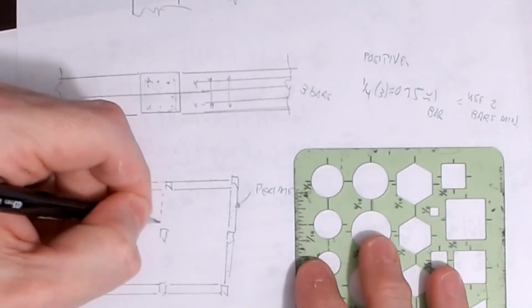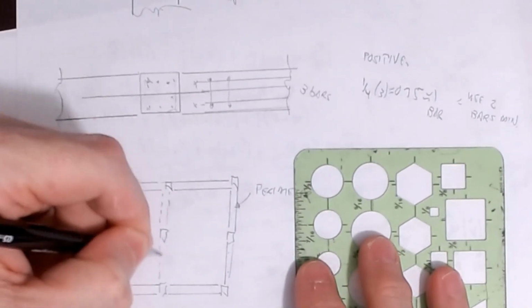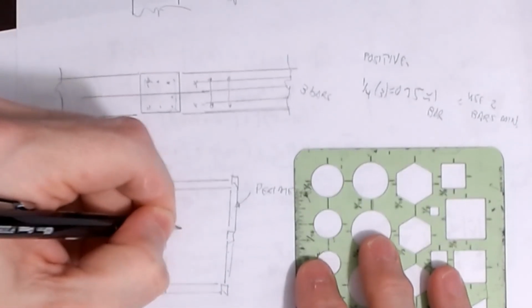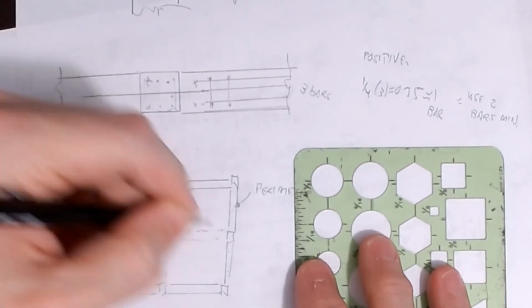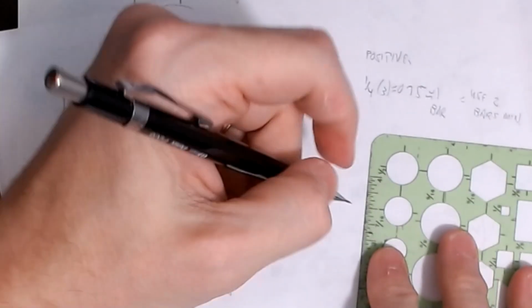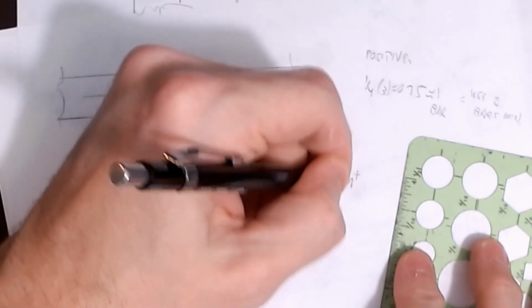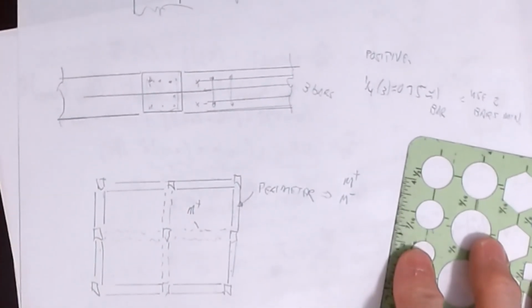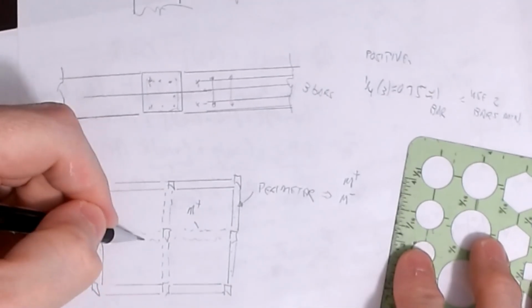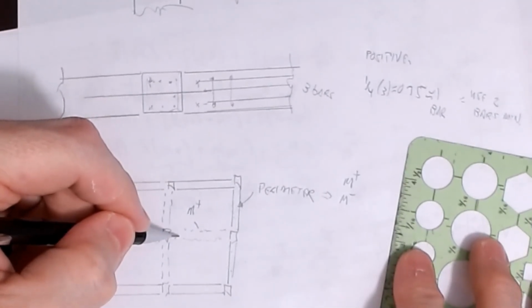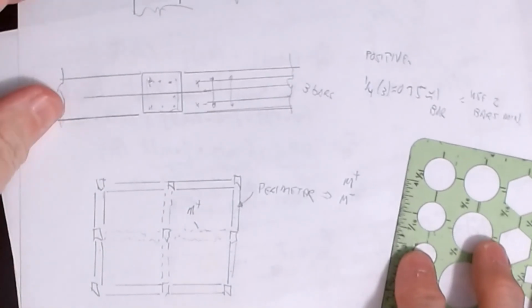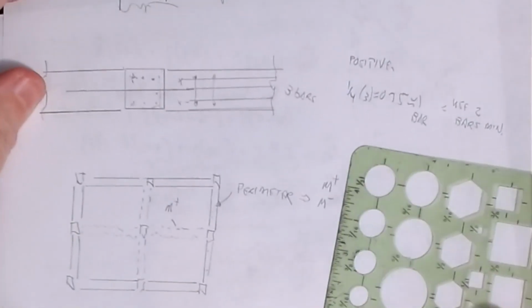The ones that are here, and I'll draw those in dashed lines, the ones that are framed in the middle are not perimeter beams, and they're bound by the other requirement. So here we're looking at the M positive requirement and the M negative. Here we're only looking at the M positive. But we still have to be continuous across the column, so I still have to continue a minimum amount of longitudinal bars from this side to this side in those beams. Does that make sense? Okay, that gets us that one.